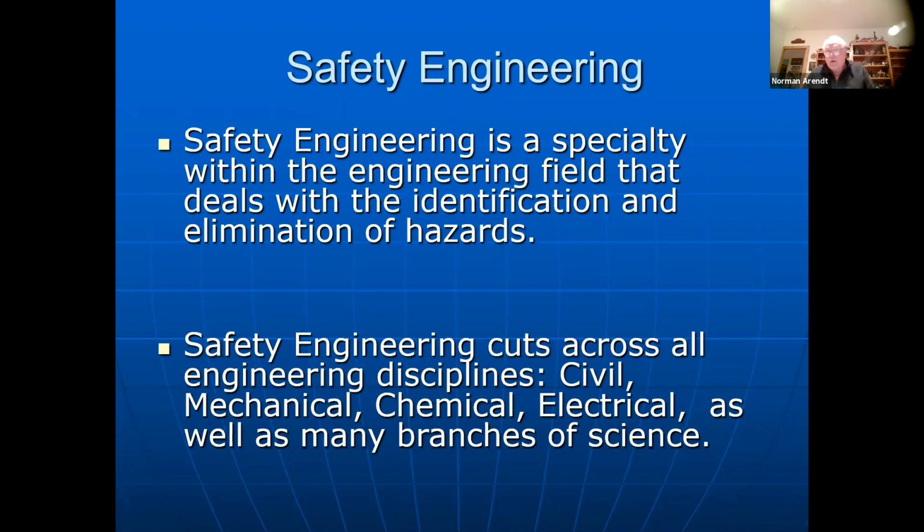And if we think of fall protection, that's the individual's responsibility to wear it. But what can we do in the design process to make it possible that they can tie off someplace, or to design the project such that they don't have to worry about fall protection? And there are things that we can do.